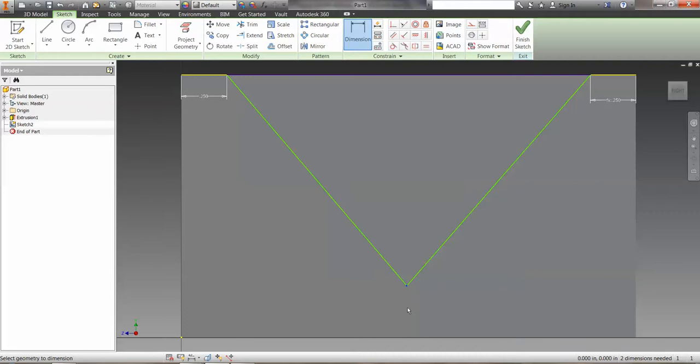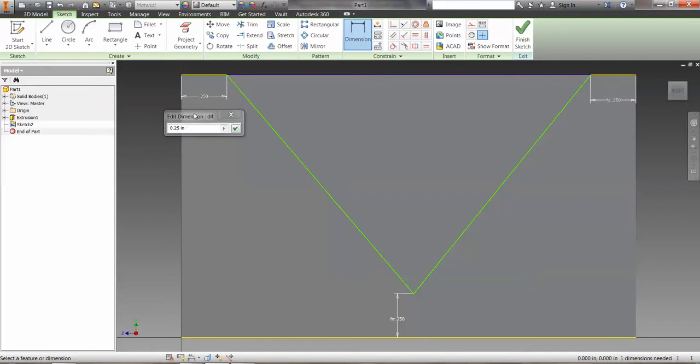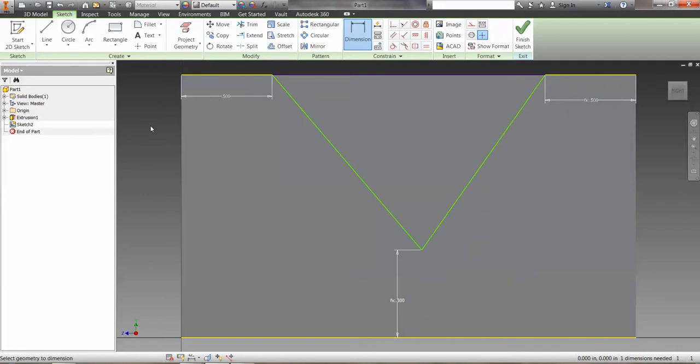So now we're going to do the same to the bottom here. We're going to set that dimension to the bottom and have it parametrically to dimension 4 as well. Nice thing about that, and you don't need to do this, just look and see, is if I change this dimension to something else, say 0.5, it changes all the dimensions at the same time because they're related to each other. It's a handy thing for other features that we might do later. So we've got that set.